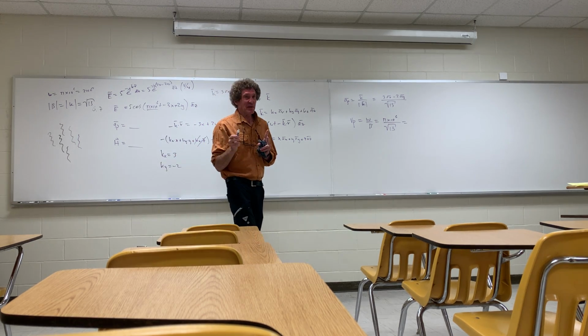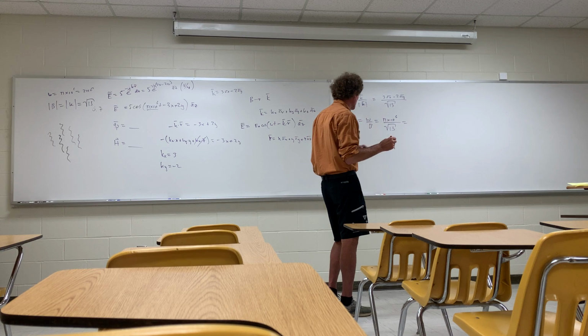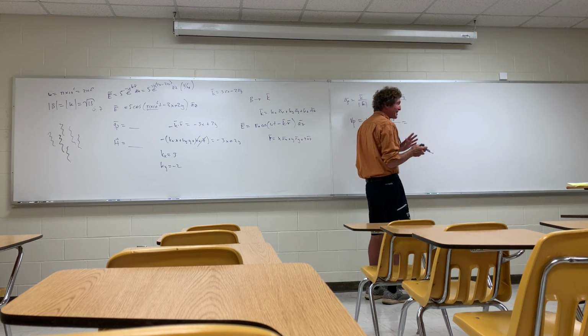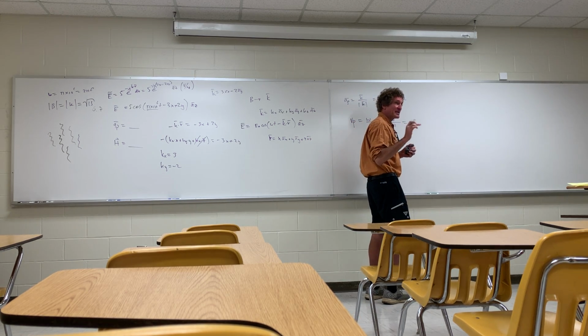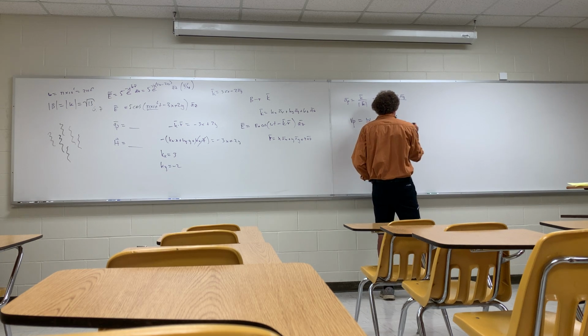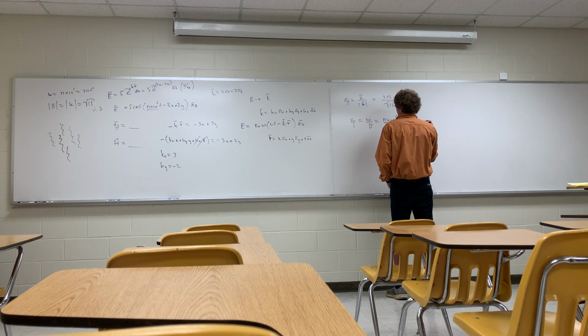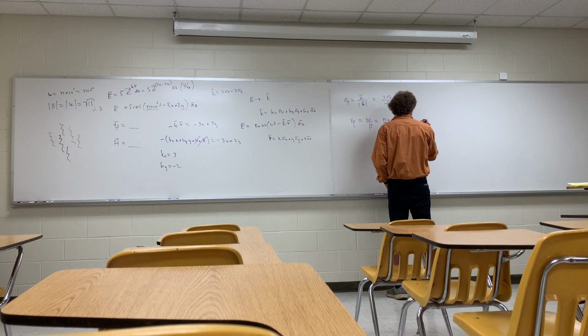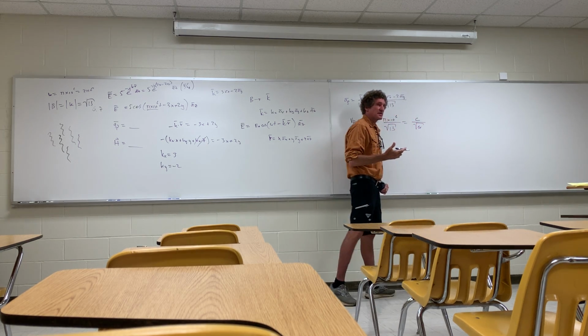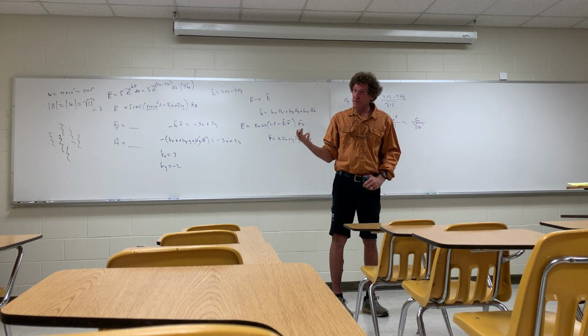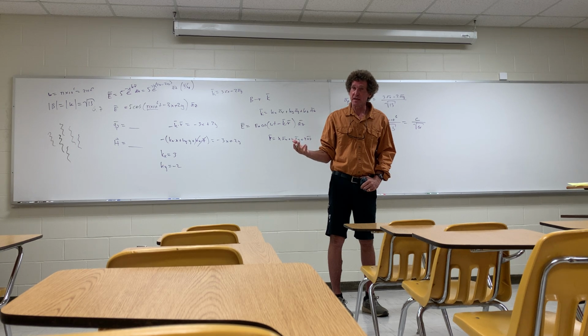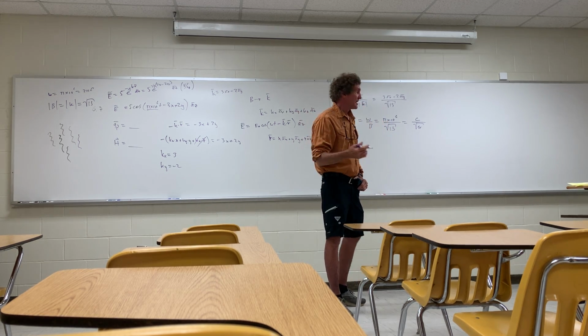But he didn't say non-magnetic, and that causes a bit of a problem. I think he meant to. And I think also this problem's going to have a screwy answer if it's exact. But if you look at this right here, the phase velocity is going to be equal to the speed of light divided by the square root of epsilon relative if it's just a dielectric, I mean a non-magnetic medium. Do y'all follow me? The thing that's going to slow it down is epsilon relative.